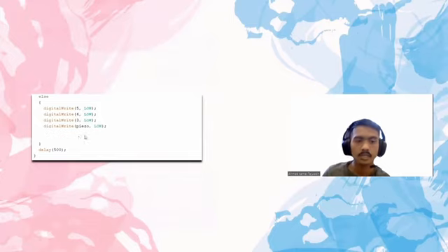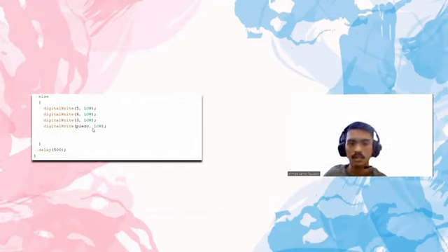And then the last one, else, as you can see here, if the touch sensor is not detected, which means there's no touch on the capacitive touch sensor, you can see that all of the LEDs will be turned off and the buzzer will not turn on. And all of this will end with a delay of 500. I think that's all for the coding. Thank you.